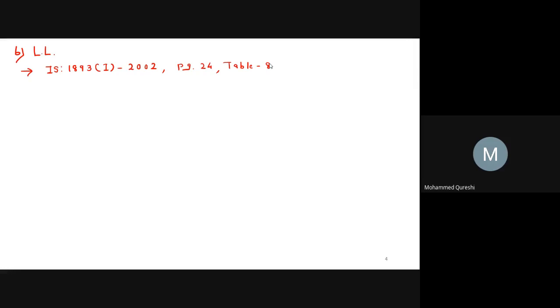So the earthquake force shall be calculated for full dead load plus the percentage of live load. So here the first case will be the imposed load or live load on the roof need not be considered. We had seen this in our first lecture.